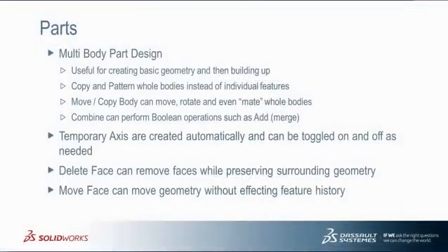We spent a decent amount of time on parts, so let's review. We discussed the benefits and a few concepts regarding multi-body part design. We saw that features like patterns can leverage multi-bodies, and Move Copy Bodies can be used to manipulate them. Then we looked at Delete and Move Face, two great tools for manipulating geometry on complex featured parts and imported geometry.